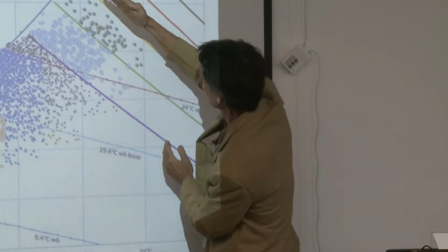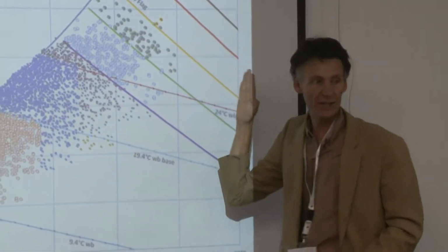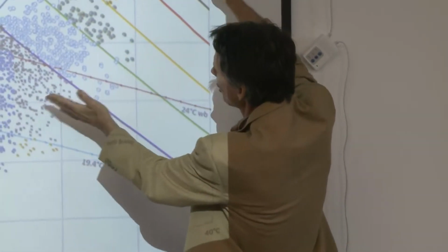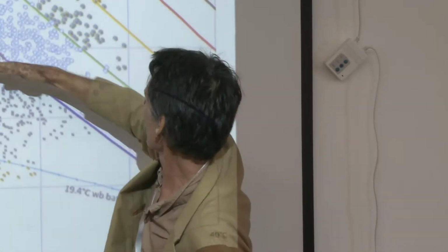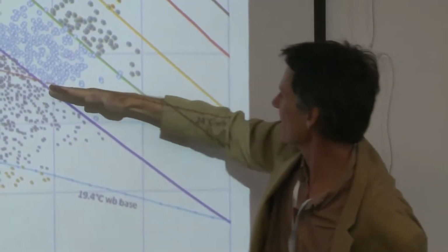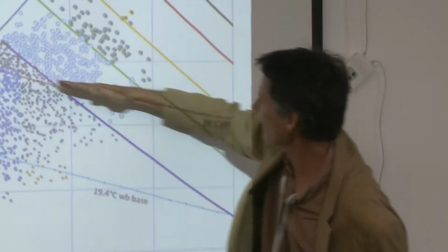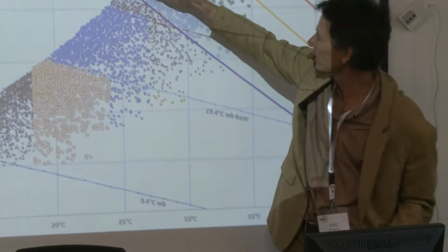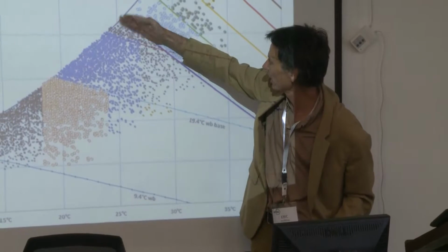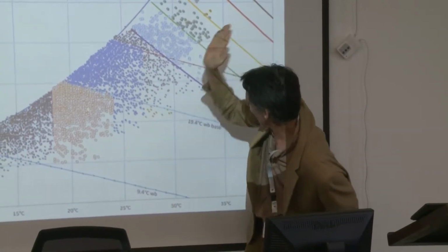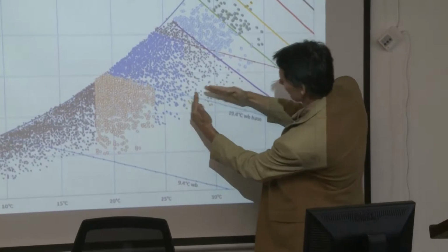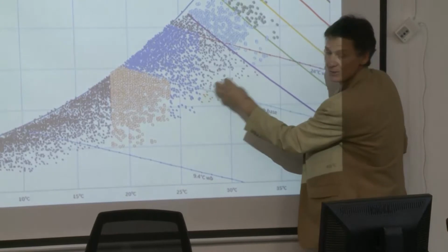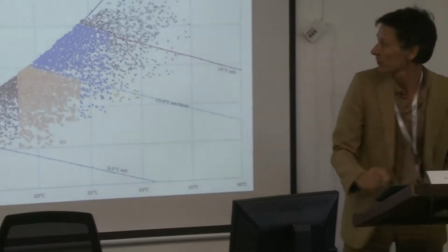Those lines are weighted by wet bulb and dry bulb, assuming shade conditions. And then we've got our classic wet bulb lines, and this is 24 degrees wet bulb, that's quite high. That's the absolute limit of what I've been able to read, where you would expect that a ventilation system would provide comfort. And in my paper I chop it off at 27 here. Down here, where evaporative cooling would work in that Chinese location, it's not many hours when direct evaporative cooling would be sufficient.